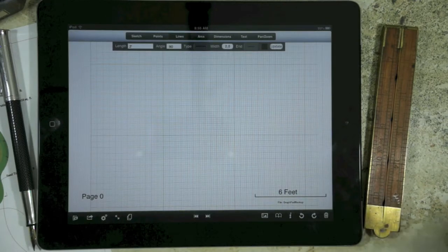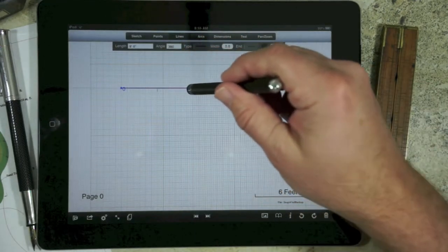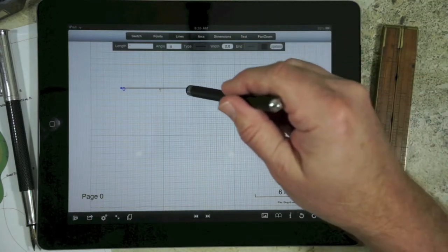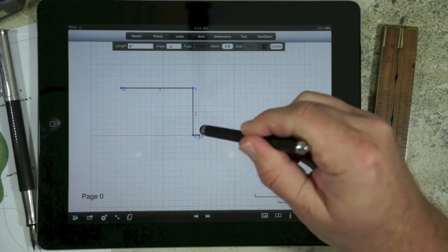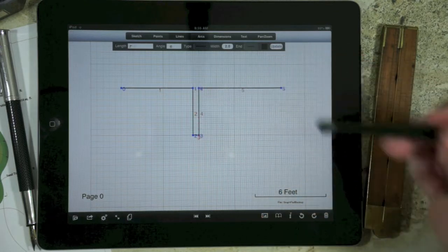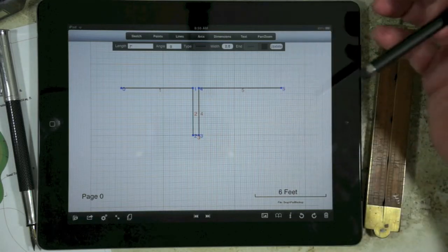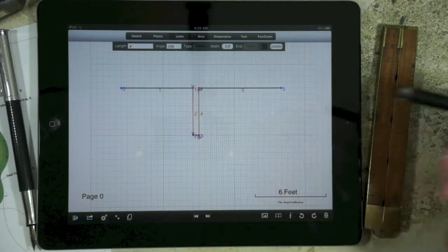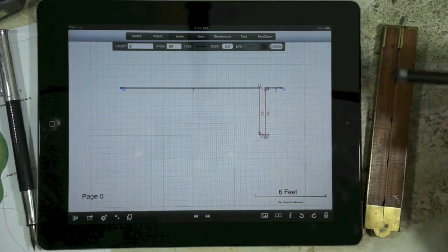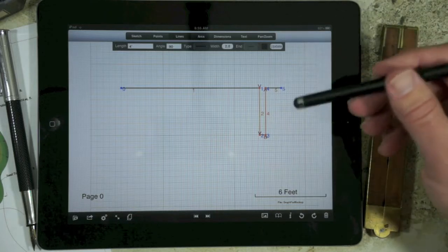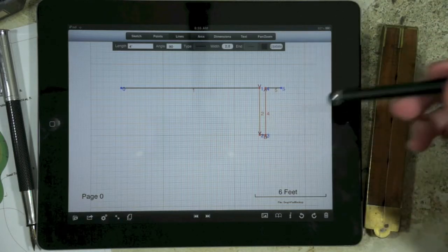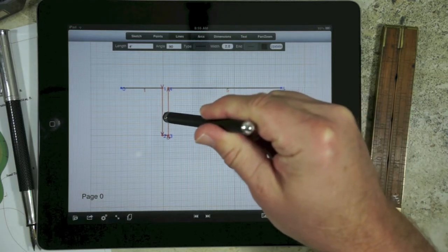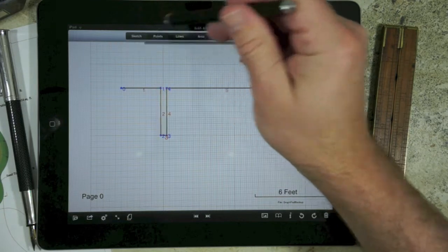Continuing on with creating geometry in lines mode, since we have our snap set to where it's 6 inches, it's very easy to create walls. So we can easily create this partition. And now we get into how we can manipulate those lines. So if we want to manipulate a line, all we have to do is select it, and then we can drag that. In this case, we've got a partition defined by 2 different lines, and we were easily able to drag that. Now, you'll notice that even though I'm moving about, it's actually snapping to the snap angle. That's defined under points.